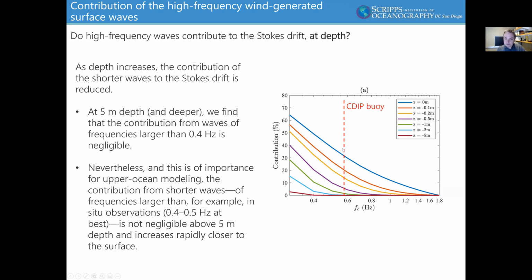However, when you get closer to the surface, and I'm putting here again the cutoff frequency of a CDIP buoy, for example, at 0.5 meter water depth you're at a 7-8% contribution from higher frequency waves. So this is not negligible and needs to be taken into account.